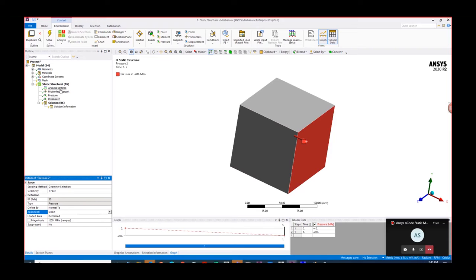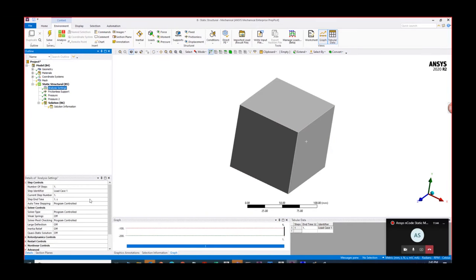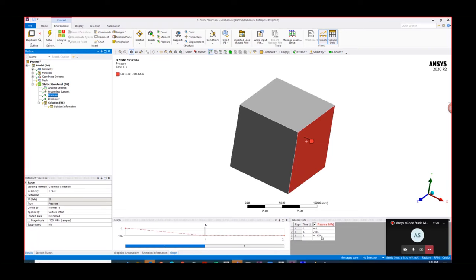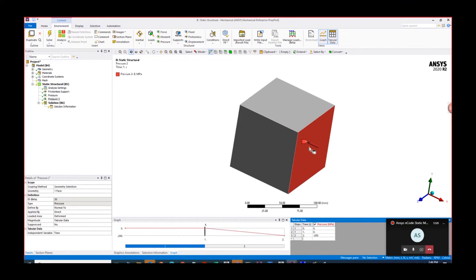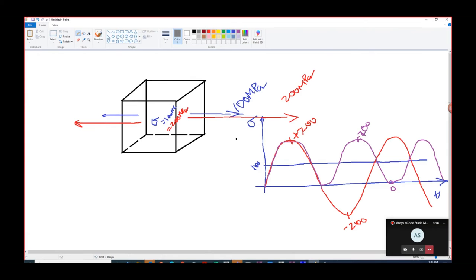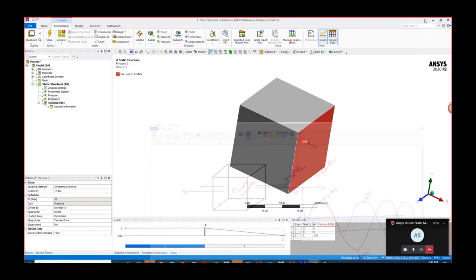Now I want to solve this as two load cases. Totally, I need two load cases. In the first load case, this static pressure is going to act, and in the second load case also. But this fluctuating pressure acts only in the second load case. In the first load case, it's kind of a 0. So I'm kind of pulling this one side. I'm going to demonstrate both scenarios: how can we handle the fully reversed loading and also the zero-based reverse loading?